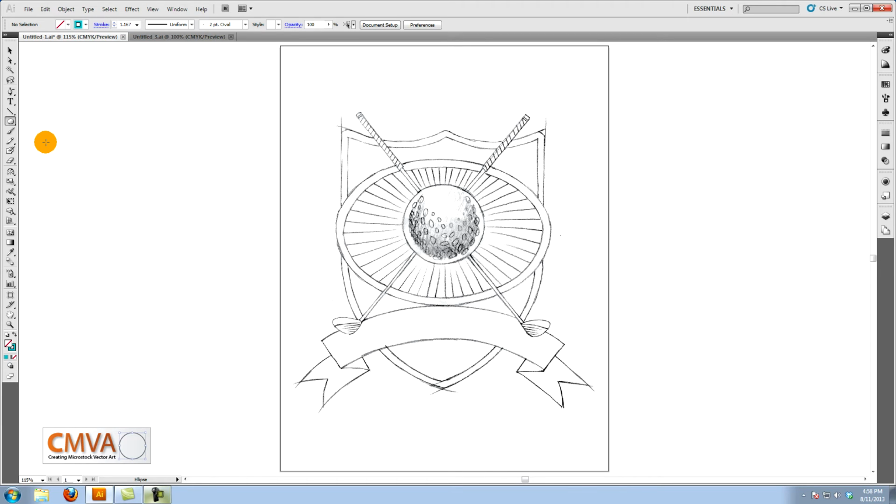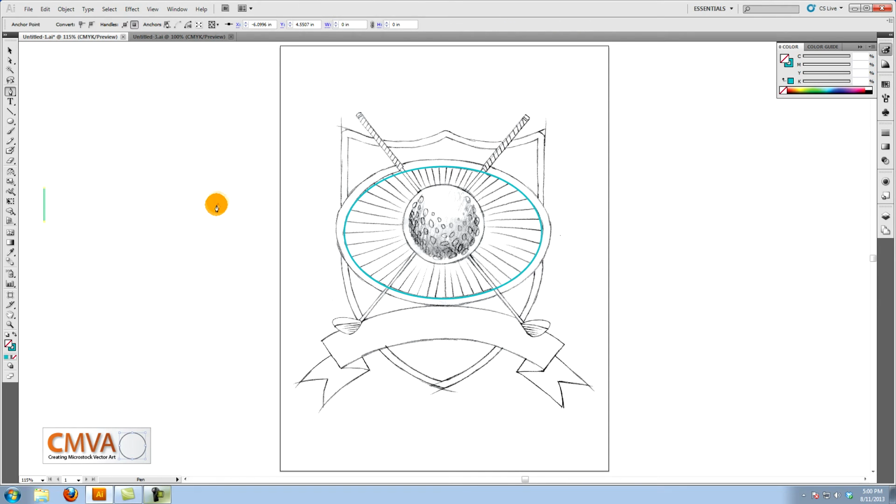Go to your Ellipse tool and give it no fill and a bright blue stroke. Create this ellipse. Use the Selection tool to adjust it to fit the shape in the drawing. Now we'll make the starburst pattern. Using the area beside the artboard, start with the pen tool and make a triangle that is 4 inches wide and 0.5 inches tall.